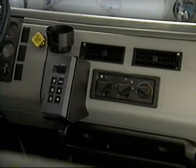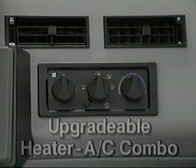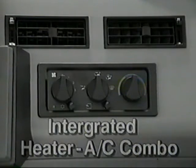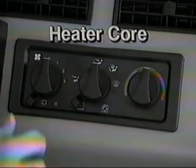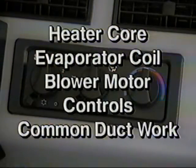All Freightliner medium trucks come standard with a bare climate control unit, which can be spec'd in one of three configurations: a standard heater-only unit, an optional heater unit which is upgradable to a heater AC combo, or an optional integrated heater AC combination. The bare heater air conditioner is a single unit consisting of a heater core, evaporator coil, blower motor, controls, and common ductwork.